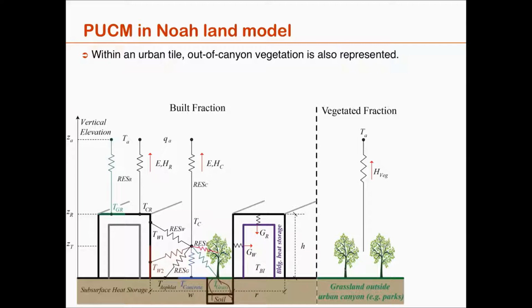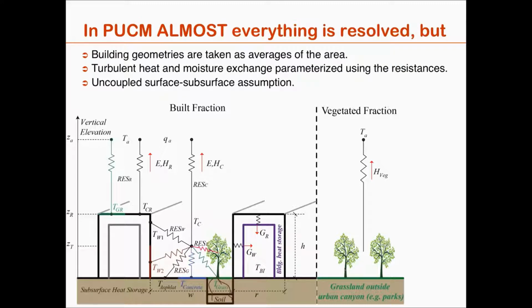So with all these details of the surface, we now have what we believe to be an extremely good urban surface model. I'll show you some of the validation later, but we've done a large range of validation looking at soil moisture, heat fluxes, surface temperature, and air temperature, and the model performs quite well, much better than, let's say, the default UCM in WRF, even though I have to say that some of the UCM capabilities in WRF have been improving in parallel to our efforts.